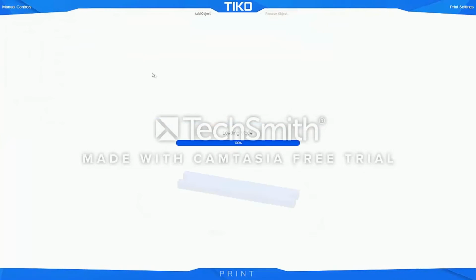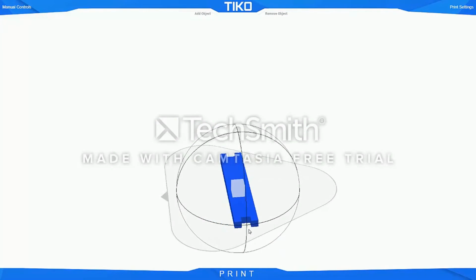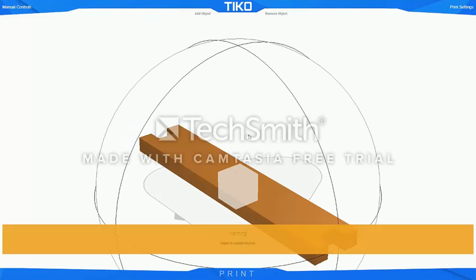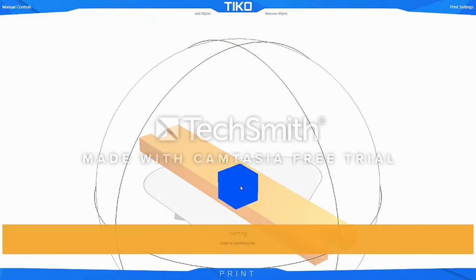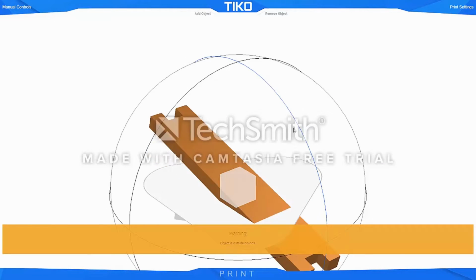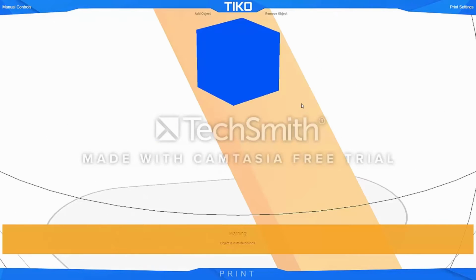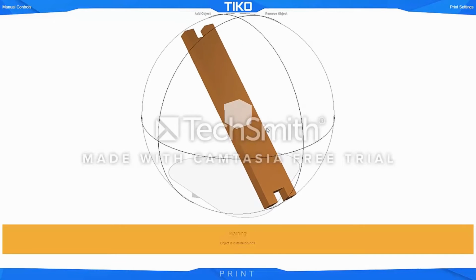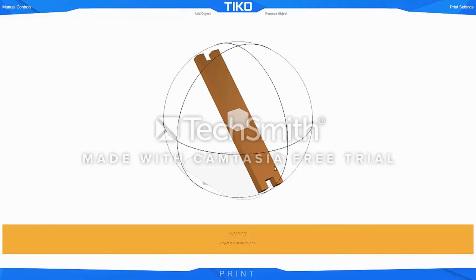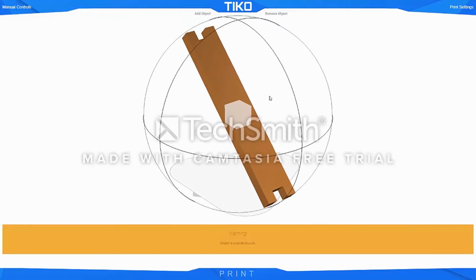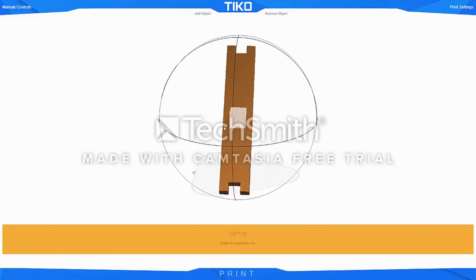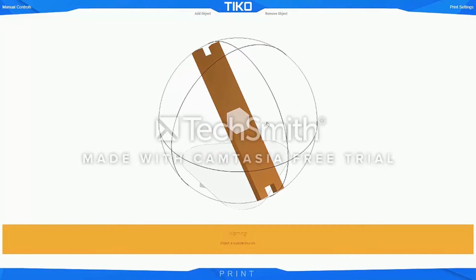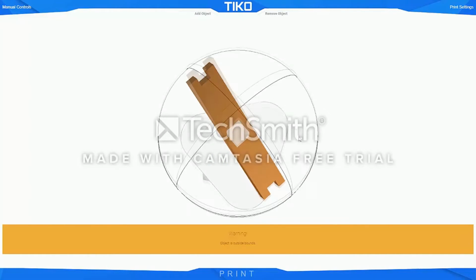So then you just double click your file. Then you have a few options. You can grab this center thing and enlarge it. When you do that, you do get a message that it's too large, and then you can rotate and it automatically centers. There's no panning. Your middle mouse, if you depress it, will move in and out, and then your left mouse button will move it around, and the right doesn't actually do anything.